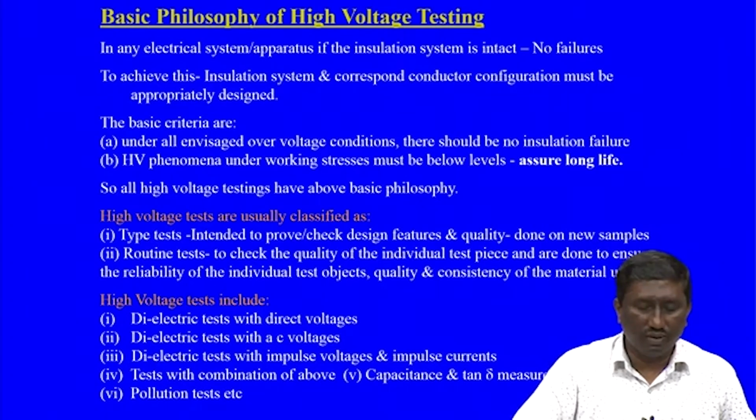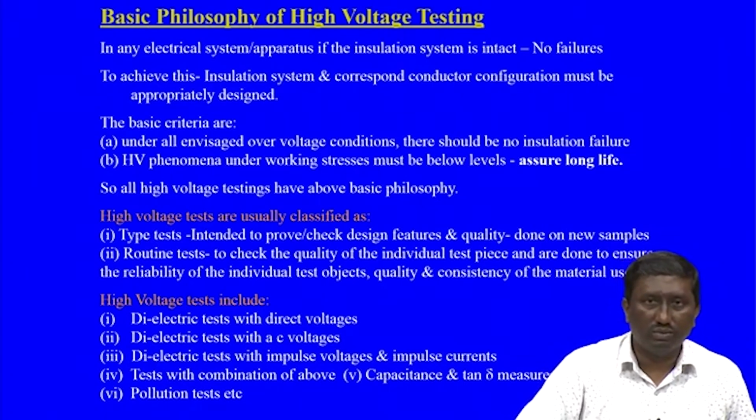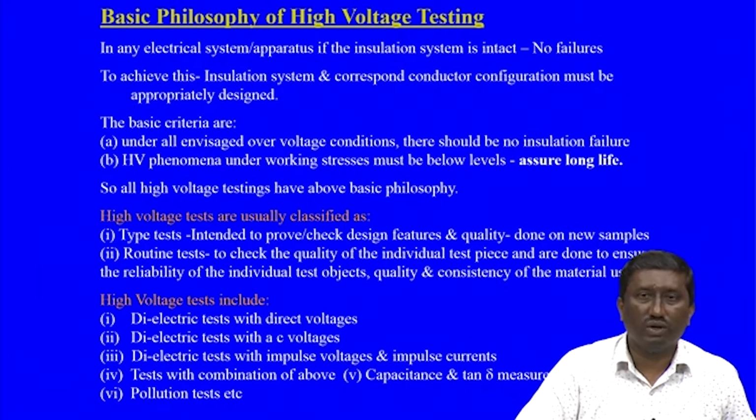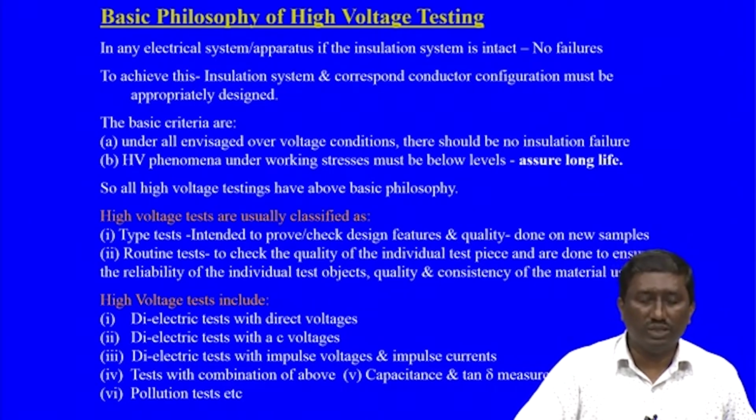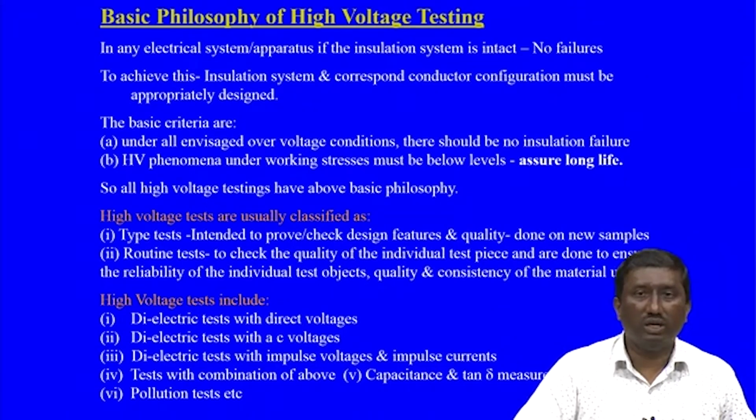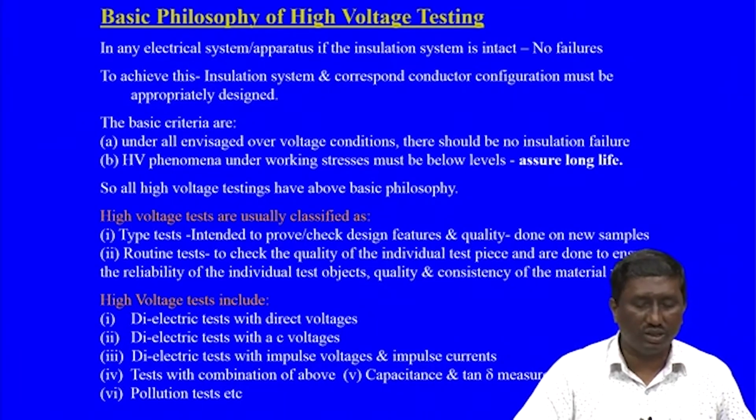So, we have earlier looked into the basic philosophy and importance of high voltage testings for the equipment. This concerns the reliability. In any electrical system, if the insulation system is intact, there should not be any failures. To achieve this, the insulation system and corresponding conductor configuration must be appropriately designed. The basic criterion being, under all envisaged over voltage conditions, there should be no insulation failure. That is an important factor to be noted here.